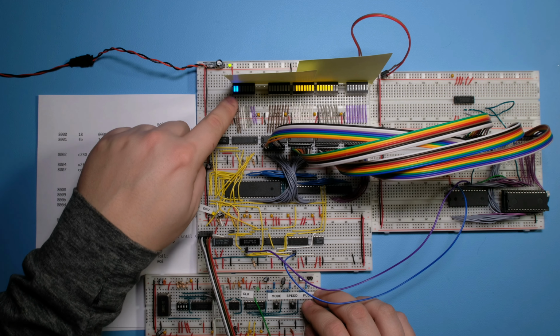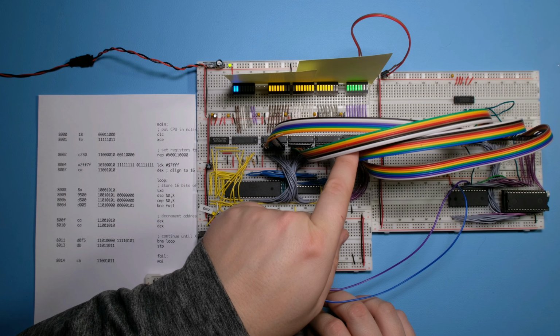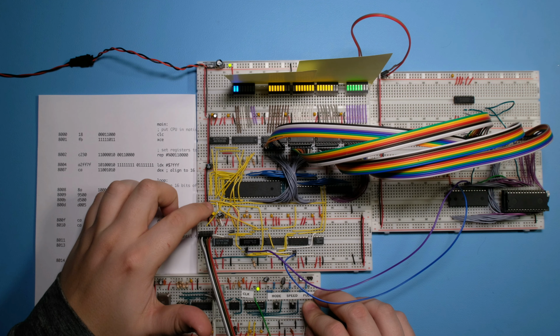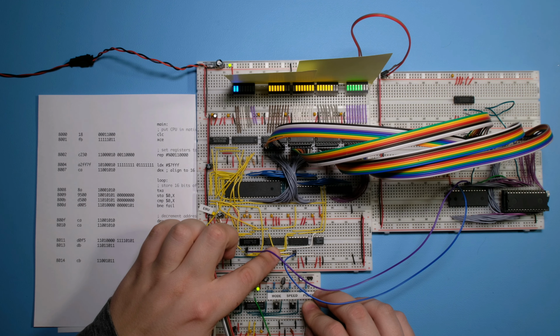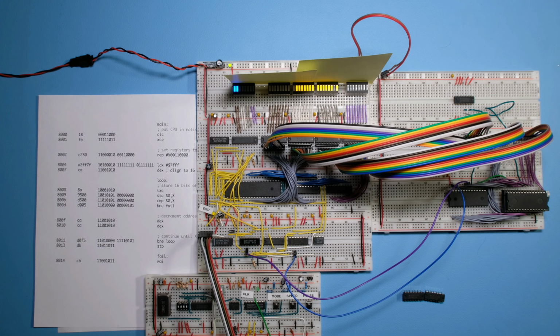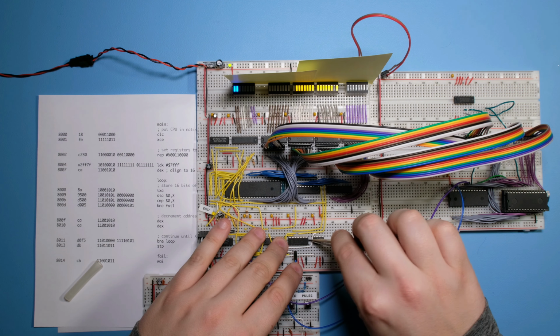The only curious thing is the bank address here getting latched. You can see it's latching what's on the data bus. And so probably this is going to be fixed by replacing those chips. Let me do that now and try it. So I have here HC11 and HC32. Let me replace those chips here.